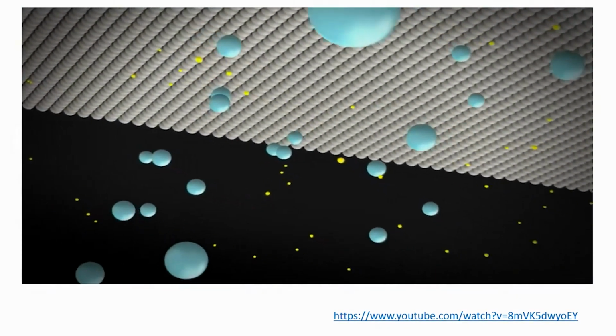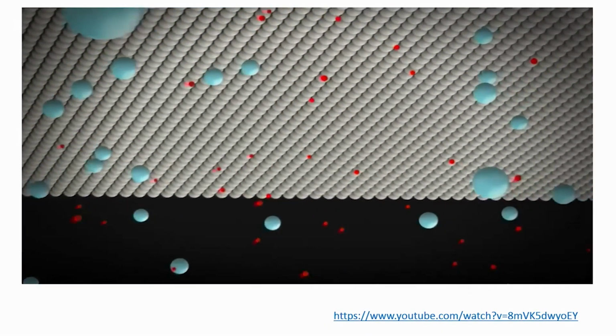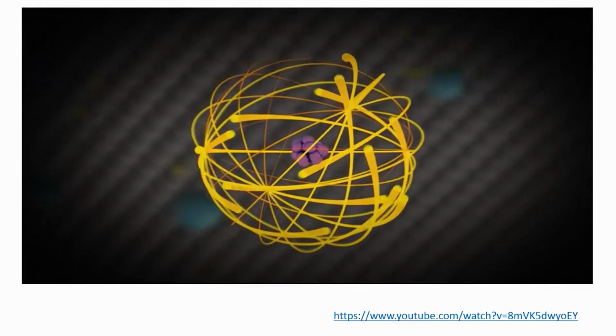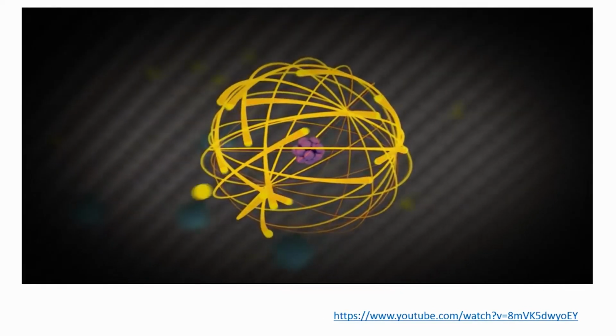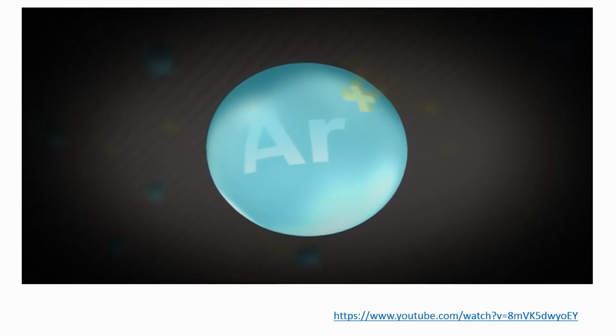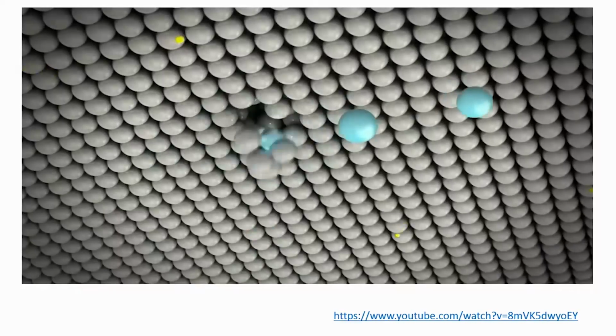The plasma consists of argon atoms, positively charged argon ions, and free electrons. The positively charged argon ions are continuously generated by electrons hitting the argon atoms. The sputtering target is negatively charged. Therefore, the argon ions are attracted towards its surface.